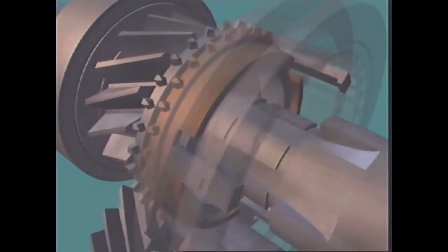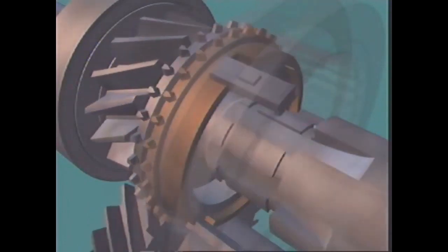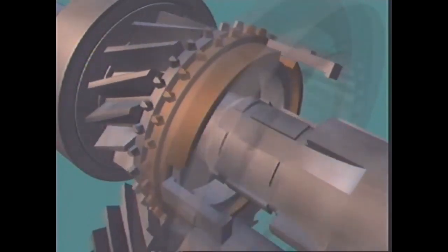The grooves in the face of the balk ring help to break through the oil film, and the difference in speed of the two components causes the balk ring to be dragged around with the gear to the limit of the recesses, where it is held by the inserts. Since the teeth of the balk ring are now out of alignment with the teeth of the sleeve, this balks or prevents the sleeve from moving over the ring into engagement.